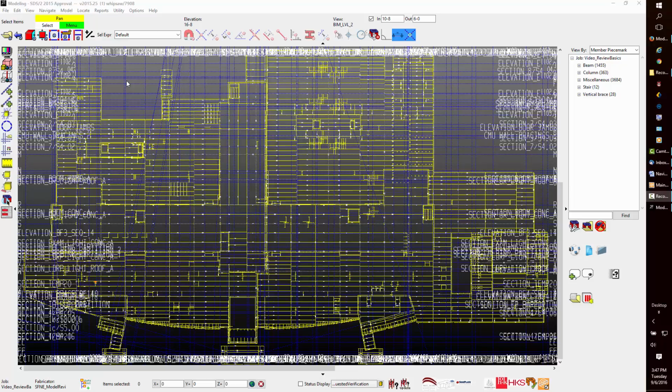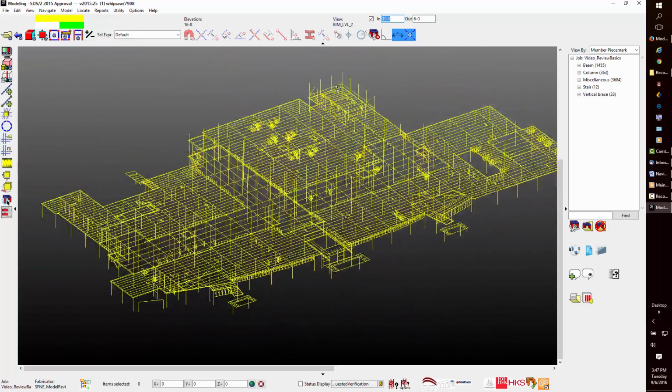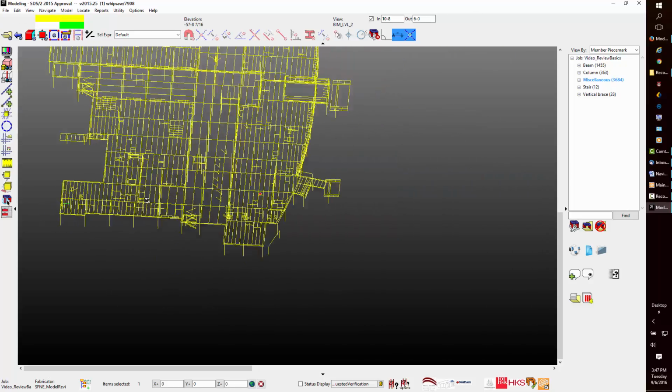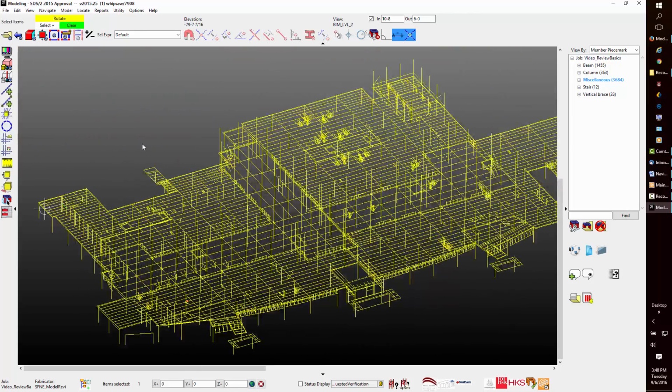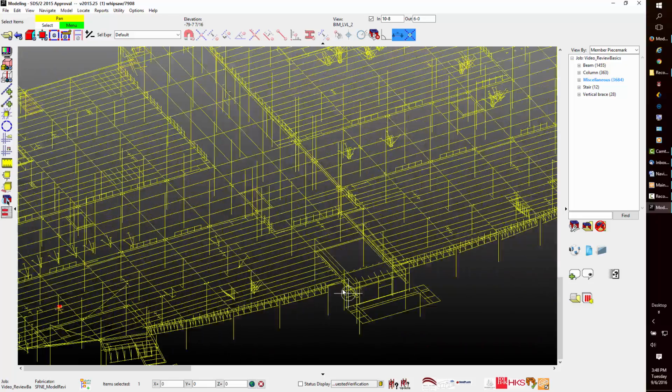While in the default Select Items mode, press and hold the Shift key to reveal the Rotate command on the middle mouse button. Then click the middle mouse button and rotate. At times, it may appear that you're rotating around some unknown location instead of the pointer in space. To remedy this, simply select an item from the model, and the rotation will then be based around that selected item. The scroll wheel will allow you to zoom in and out of the screen, focusing on the mouse pointer location.